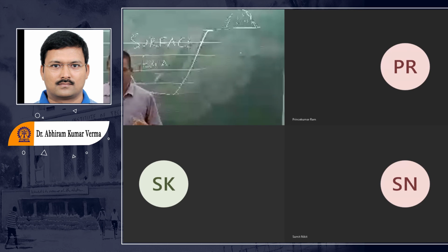We can find out what is the zone around the excavations which is being affected by such type of excavations. So that area is very important. What is the area around the opening that is getting affected by such excavations? That area in which the stress field has changed, we are calling a zone of influence.